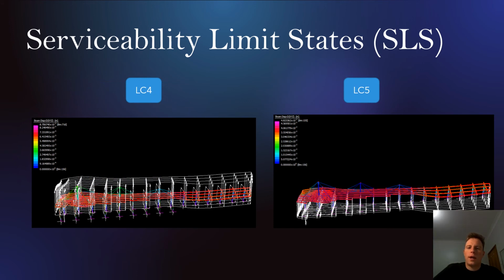Again, from load combination 4, with the presence of a wind uplift force, there are multiple forces occurring in the upward y direction in the structure, as we can see around this section of the model. And then opposingly, through load combination 5, while being concerned with the self-weight and live loads throughout the structure, this displays multiple downward force lines affecting the structure, as we can see throughout here.